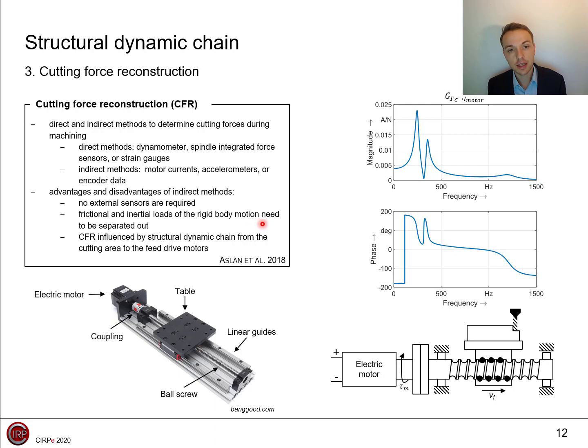In addition, the structural dynamic transfer behavior from the cutting region to the feed drive motor must be considered. To be more precise, the shown transfer characteristics from the tool via various mechanical components and couplings to the feed motors must be determined. Otherwise, no dynamic forces can be measured.